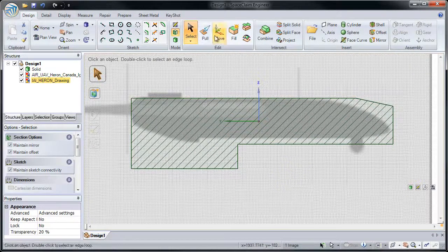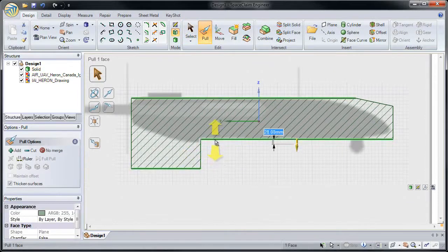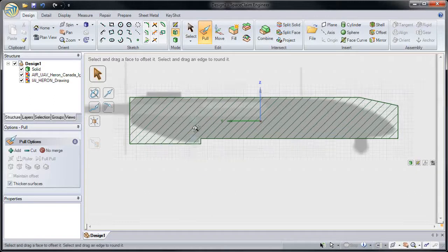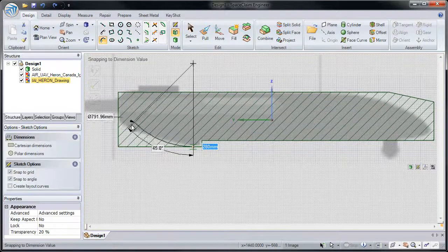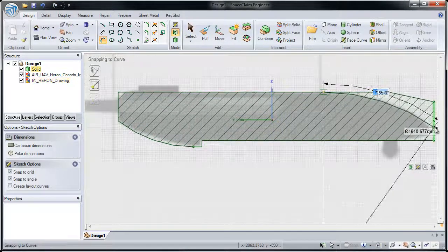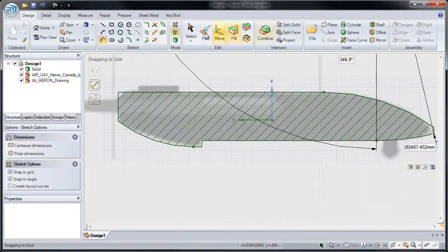We can use our pull tool and move tool that we saw in 3D in this convenient 2D cross-section, dragging on faces and edges and snapping them in the model. We can even sketch to edit this 3D solid and use these curves to cut away parts of the solid, further shaping the image to what we need it to be.